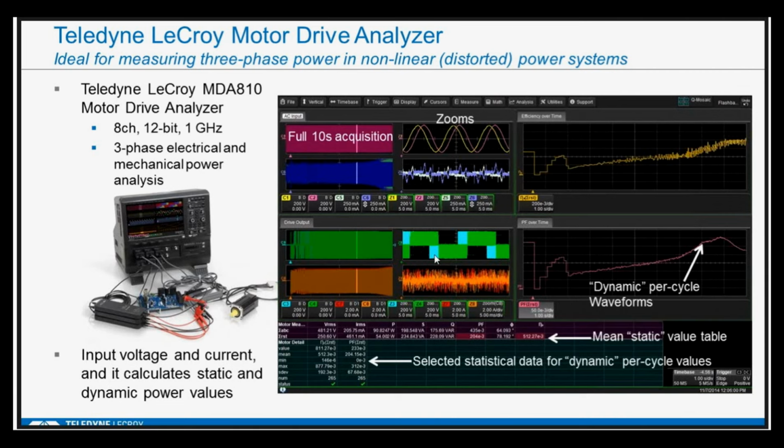And this is the drive output here. This is the voltage envelope right here for the 2 lines I'm measuring. And then this here is the current. It looks pretty noisy. It is. It's drawing a relatively small load. There is a lot of noise pickup just in the environment from all the switching activity. But that is the current right there. You can kind of see the sine wave being delivered like that.